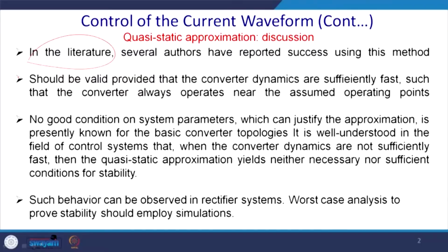Today we are going to continue with the PWM rectifier, that will be our third lecture for single phase. Where we left off in our previous class, we will start from the current control waveform. As you have seen, there is an inner current control loop that is fast in response, and an outer voltage control loop that is slower in response, and implementation is easier for this boost converter. So, if you study a little bit of the literature, you will find that several authors have reported